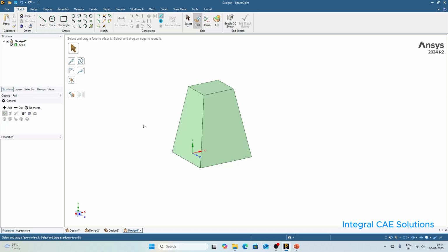The main point to note is that those parts will be different solids. Likewise, in simulations too, oftentimes we need separate solid bodies or fluid bodies for different parts, for applying different types of meshing methods or different boundary conditions.